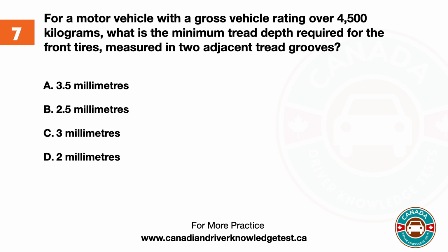Question 7. For a motor vehicle with a gross vehicle rating over 4,500 kilograms, what is the minimum tread depth required for the front tires measured in two adjacent tread grooves? A. 3.5 millimeters. B. 2.5 millimeters. C. 3 millimeters. D. 2 millimeters. The answer is C. 3 millimeters.